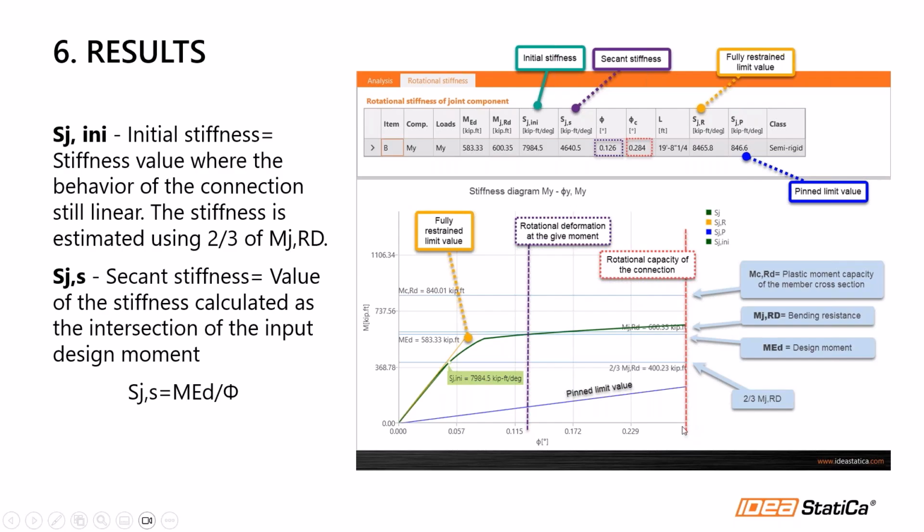Remember that to calculate this rotational capacity, we use a higher limit, that is 15% of plastic strength, right? So that's why we need these two types of analysis behind the scenes, because we get the moment capacity and the rotational capacity, okay? Now, the L is the theoretical length that we explained before, and then we have these limit values, right?